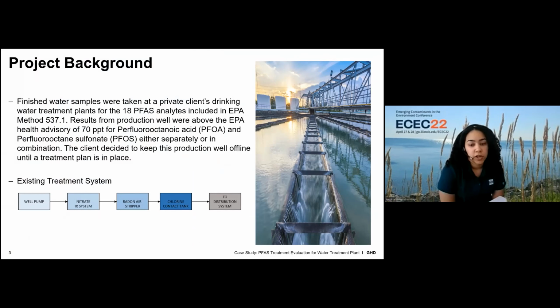Now, a little bit about the project background. The client is a municipality owner located in the Mid-Atlantic region. It is a private client, so a lot of this information is minimal and proprietary, so that's why there's not too much detail. However, they were requested by their state regulator to perform PFAS analysis at their water treatment plants, and one of their water treatment plants was detected with limits above the EPA standard, which is the 70 parts per trillion for PFOA and PFOS.